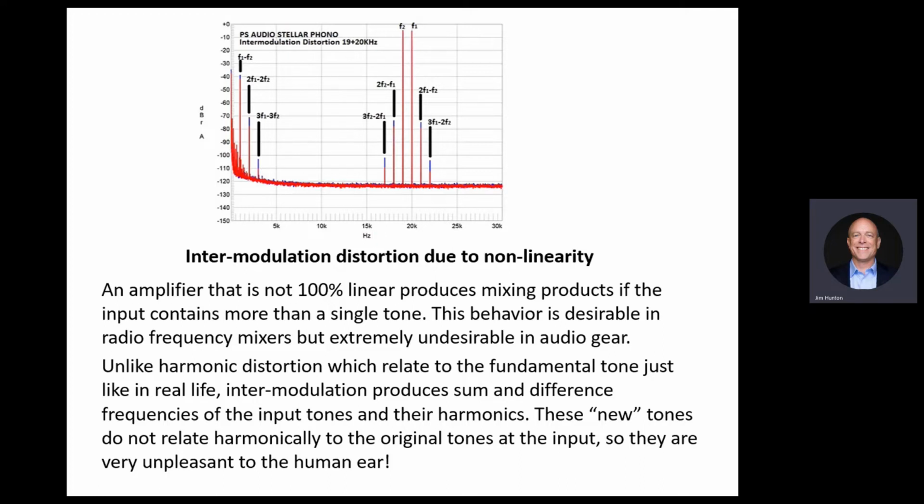We see a second harmonic of both of them mixing, and the higher harmonics are at lesser level. But we do see a content of intermodulation like that. This is intermodulation. 2 tones coming in, they generate the plus and minus of those tones. Why are we differentiating between those and the harmonics?